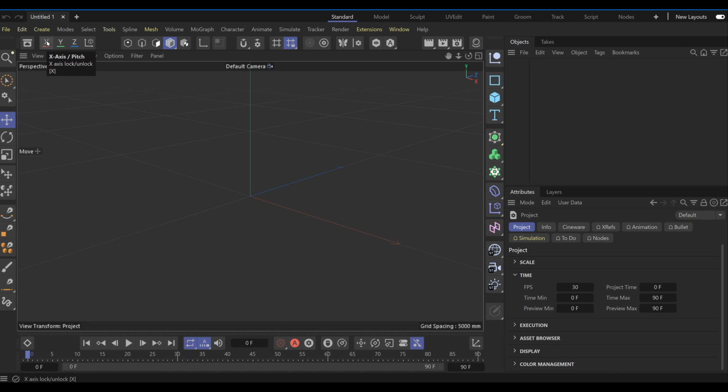To the right of this are the axis locking icons. Remember that we're talking about a viewport that we're going to have objects and environments that we're building in. So there are times that you might want to have to lock one of the directional axes. And you can see that in fact the red, green, and blue, the X, Y, Z axis, each have a corresponding angle here that allows you to lock it.